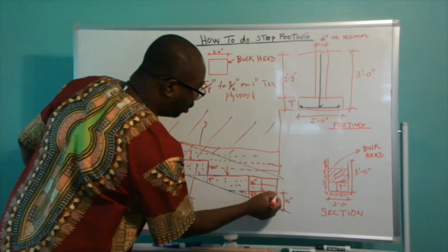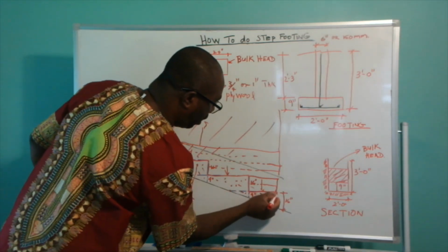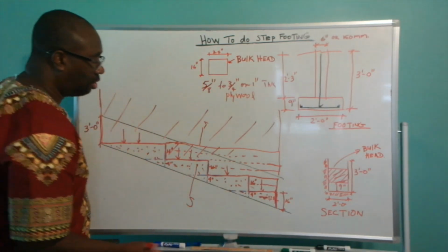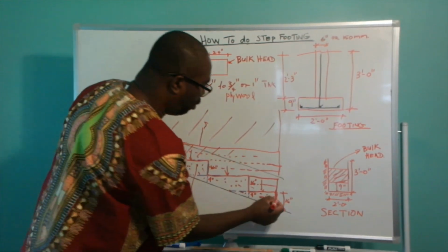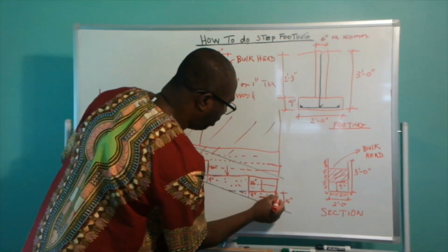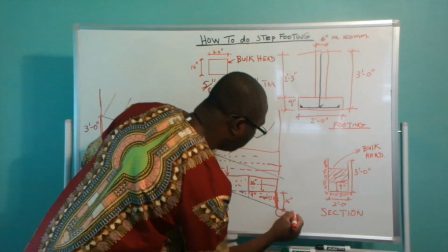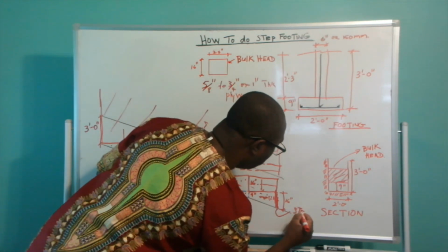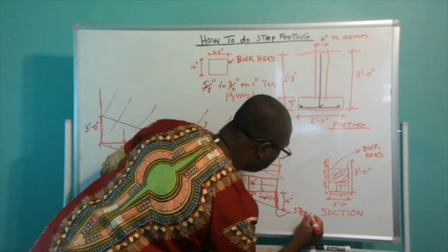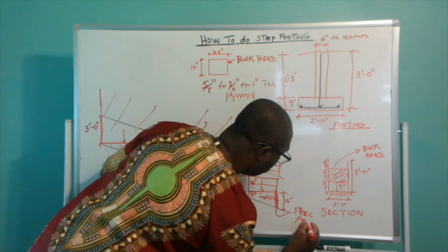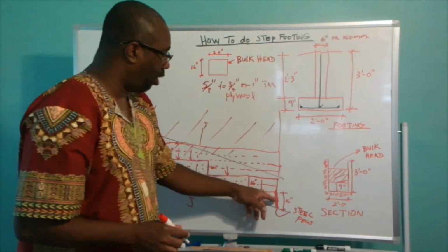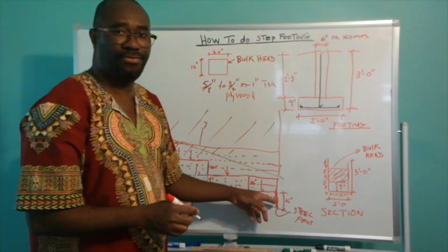But ensure that the bulkhead that you have placed right here, ensure that you put 2 steel pegs behind it, to reinforce the plywood that forms your bulkhead.